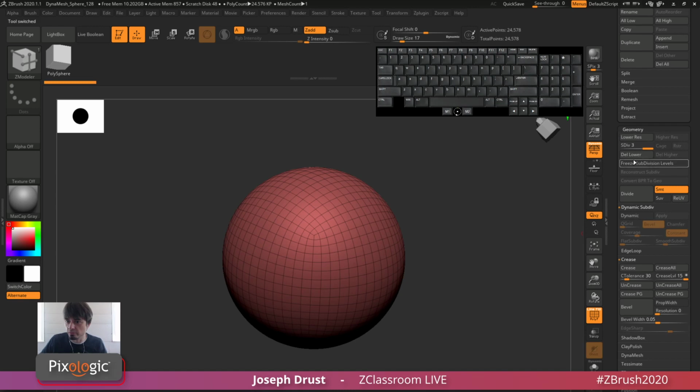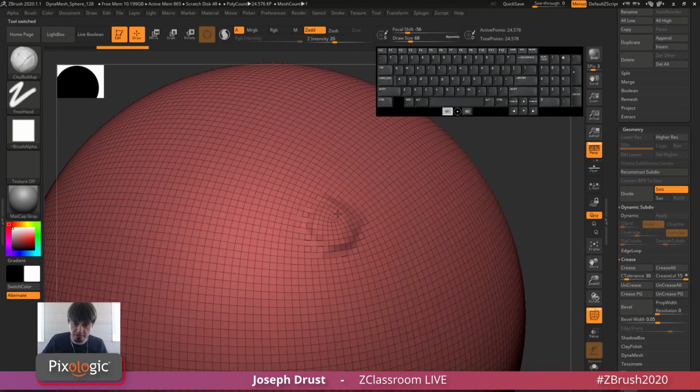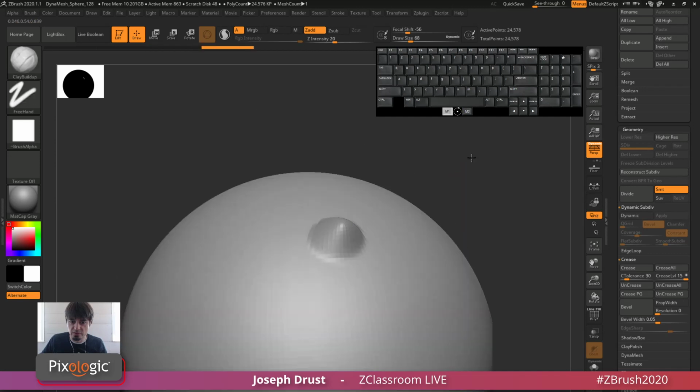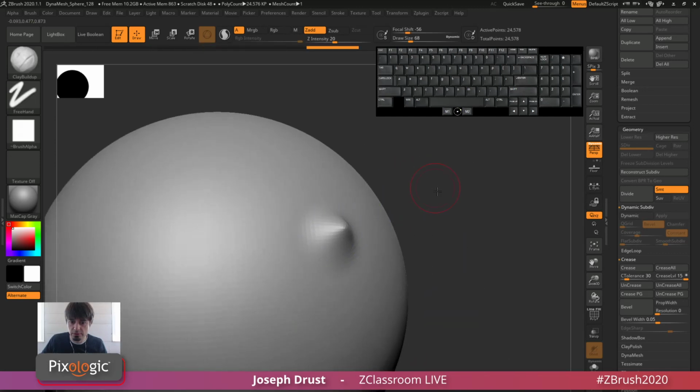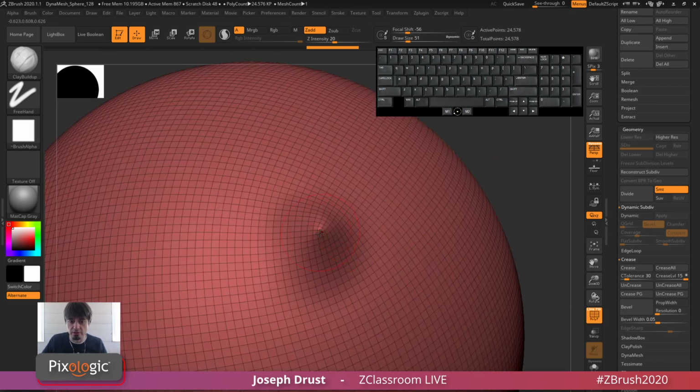Let's get this quick. Tangent mode. We always got to have some tangent. Let's see if I can get this to do it. So let's say I smooth this out. And you can see with the topology here, I'm getting this little point. And this is because the underlying geometry has all these points going together. And so this other area is smoothing really nice because they're all nice quadded surfaces going in like a very straight city. And the point here in the middle has like 3 edges going to 1 point. So it's irregular topology based on the surrounding area.